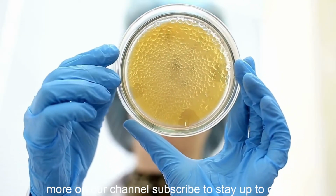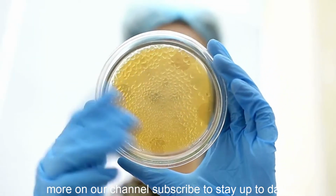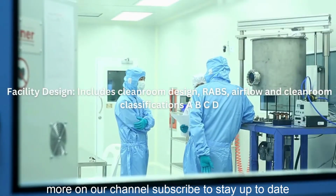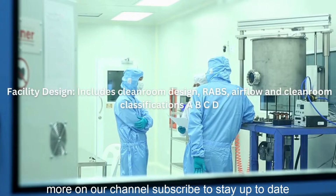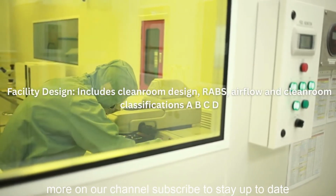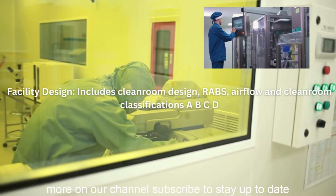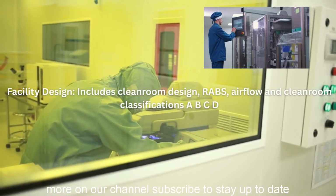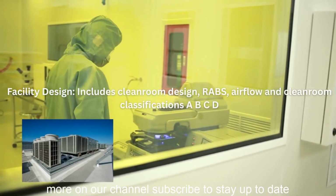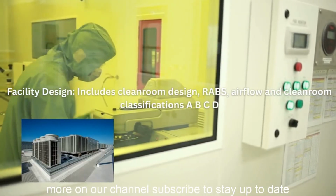Annex 1 covers a wide range of topics, providing detailed requirements for every stage of sterile manufacturing. Here are some key areas. Facility design. Annex 1 places a strong emphasis on the design and layout of manufacturing facilities. This includes the design of clean rooms, the use of barrier technologies like isolators and restricted access barrier systems (RABs), and the control of airflow and pressure differentials. For instance, it specifies requirements for airlock design, surface finishes, and the segregation of incompatible activities.